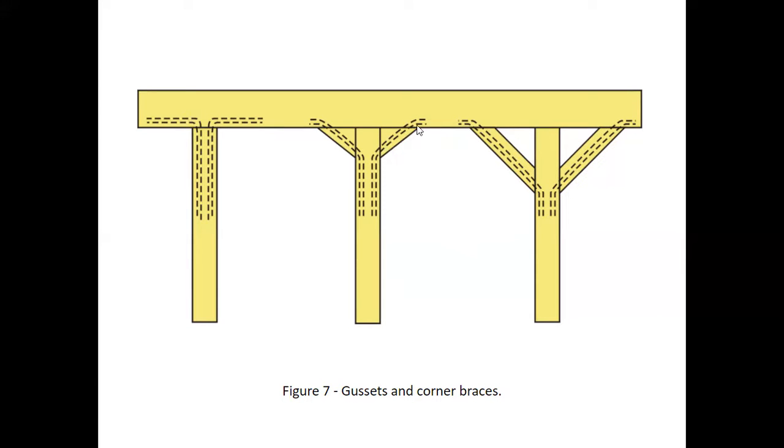We want to add in gussets. So these are gussets. They're basically steel fins that go in here to weld them into place, and it helps distribute the force and the stress. And these here are what we call knee braces. This will get put in place and welded on all four sides. This will be the same material as this normally, or pretty close to it.